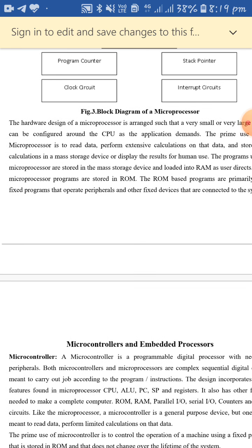Next, packaging, in the sense of how the IC is going to be manufactured, whether it is a quad package or dual in-line package. Next, availability of software development tools such as compilers, assemblers, and debuggers. This is the software part you add to every microcontroller to make the hardware work. Here you run different programs using the assemblers, debuggers, and compilers. These development tools should be easily available in the market to run all the programs, and to check whether the program works as per our requirement or not.